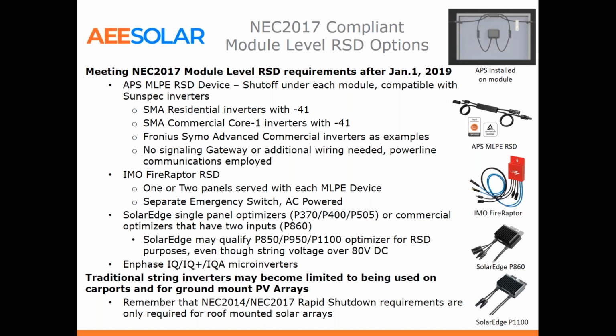For smaller projects, specifically 3-phase 208 or single-phase projects, you also could use N-phase microinverters, especially if the array is broken up or basically lends itself to a microinverter type of environment, or if there's steady shade conditions there, N-phase could be an option there. Anyway, string inverters, the traditional ones, we see them now being limited to use on just carports